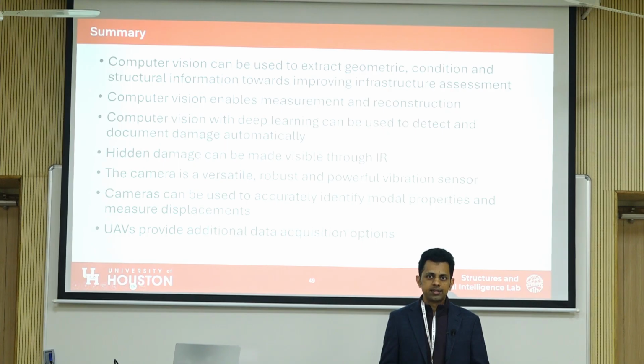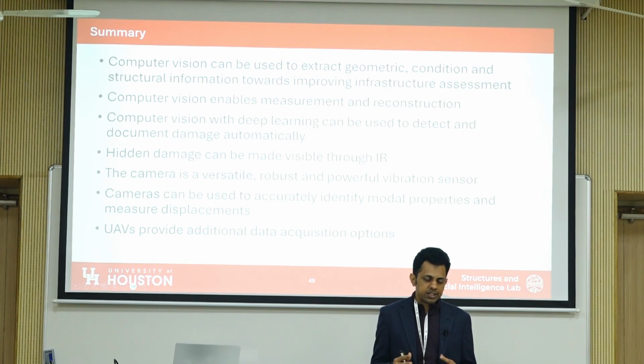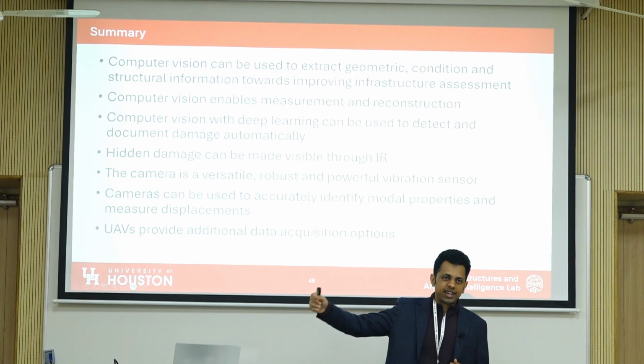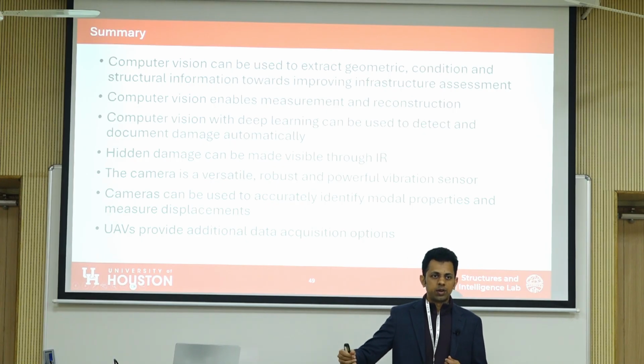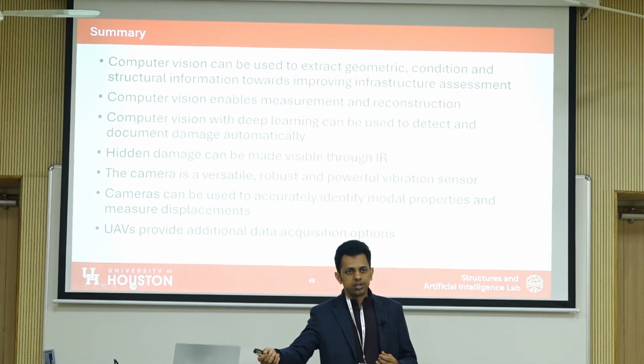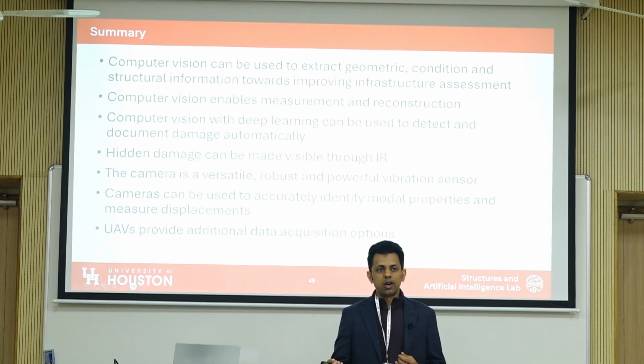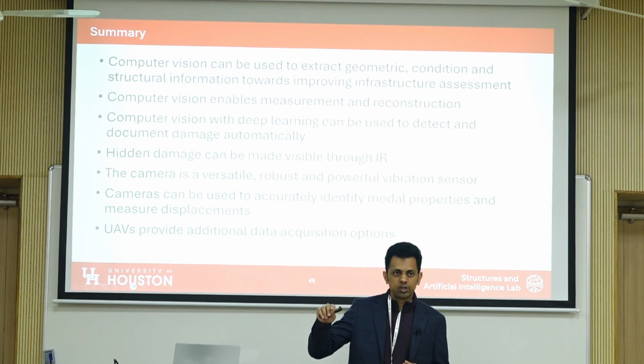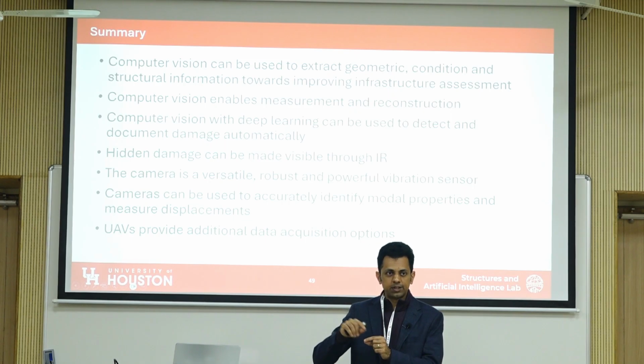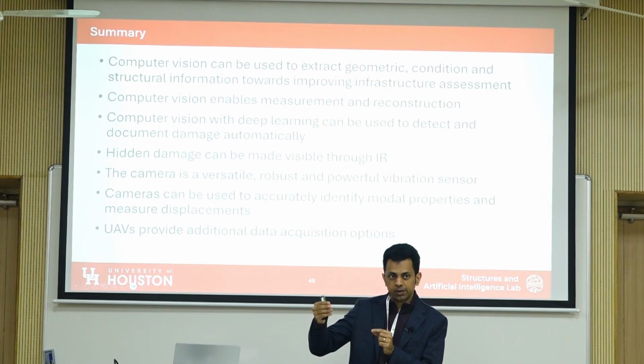But otherwise, one problem with civil infrastructure is it's difficult to do active thermography. Active thermography is where you provide the heat source, and what that allows for is non-equilibrium heat change, right? Because when you apply the heat source, the rate of change of heat is going to be different, and so you can observe that.